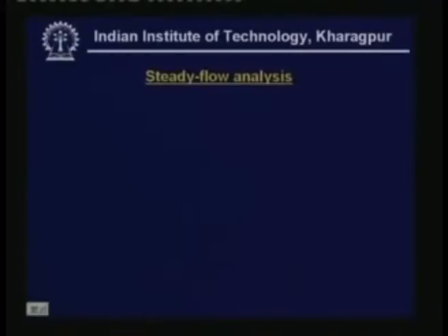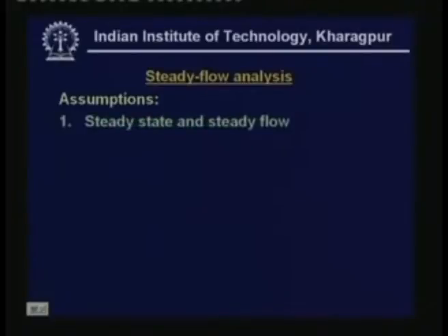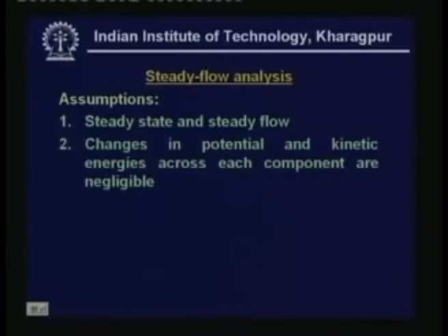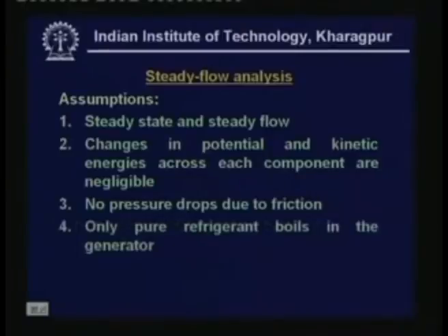Now let us look at steady flow analysis of a simple single stage vapor absorption refrigeration system based on water lithium bromide. And first let me list out the assumptions made. The first assumption is the usual assumption, it's a steady state and steady flow process. Then changes in potential and kinetic energies across each component are negligible, and there are no pressure drops due to friction, and finally only pure refrigerant boils in the generator.